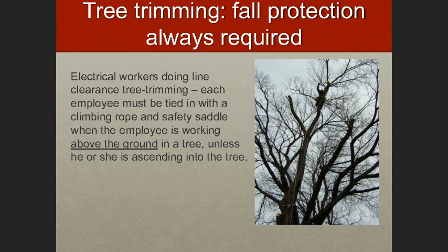Tree trimming, if you're ever involved in this, whether it's outside of the office, you know, we have an employee go out there and work on trimming some trees just as a collateral duty or just because it needs to get done. Remember that we have that employer-employee relationship, so the OSHA regulations come into play. So anytime there's tree trimming, fall protection is always required.